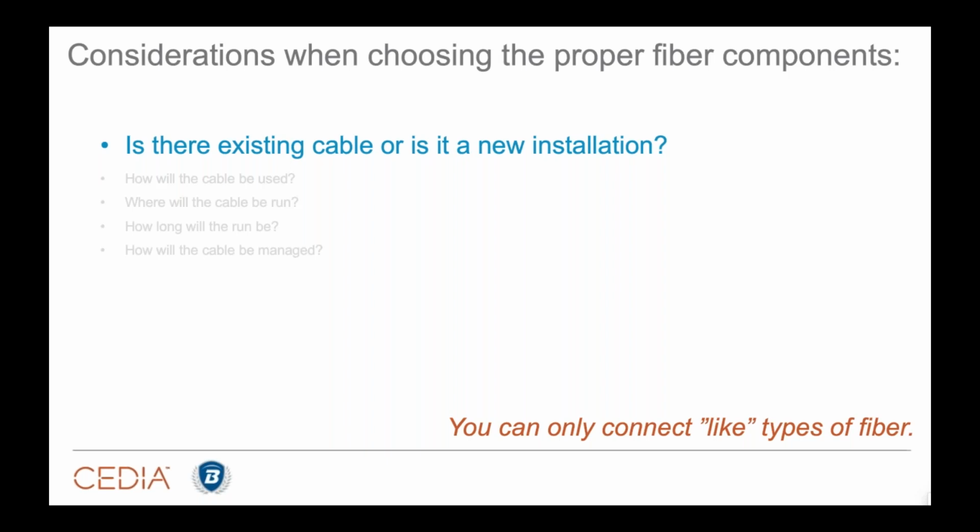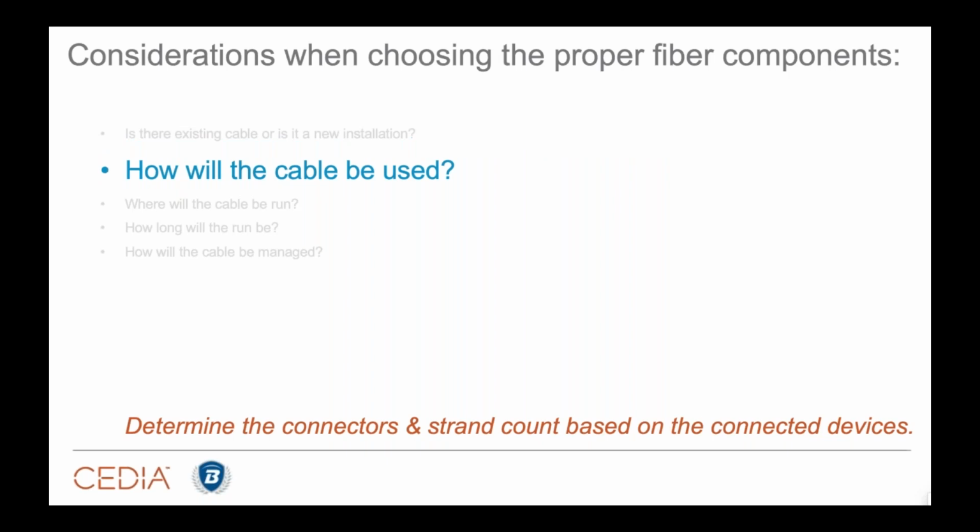This is pretty important because if you are going into a retrofit and there is fiber that's already existing in place, you want to make sure that you're using the same type of fiber. If it's blue, odds are it's going to be multi-mode fiber. Multi-mode only splices and couples to other multi-mode cables. Single mode, this one's typically yellow. Single mode only splices and couples to single mode cable. So if there is already fiber in the wall, in the rack, installed in the project, use the same type of fiber. And this is a big part of the other courses that we offer. We really walk folks through this topic to make sure you're designing and you're installing properly.